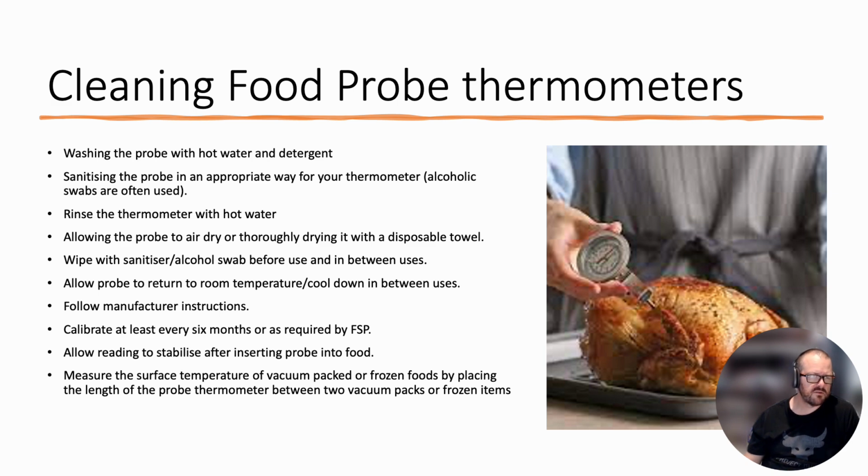Pretty similar stuff for when we're using it as well. Wipe it with sanitizer before use. Follow the manufacturer's instructions. Calibrate every 6 months or as required by the food safety program. So that could be something that's in the food safety program. And allow readings to stabilize after inserting the probe into the food.